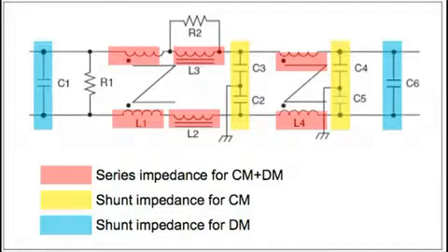Layout of the filter is also very important to avoid inadvertent parasitic coupling. Typically, engineers will measure the electrical characteristics of the device to allow calculation of the optimum component values. More information about these calculations is given in Application Note 22, which is available on the vicorpower.com website.